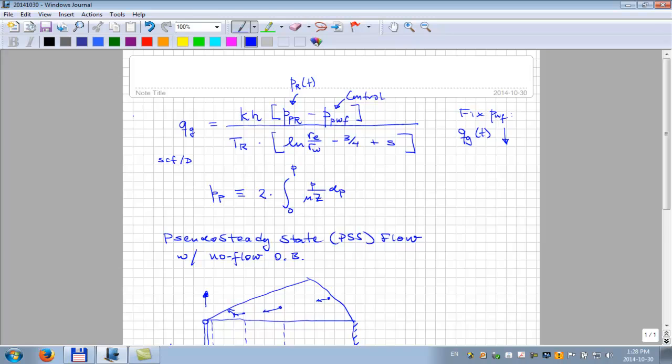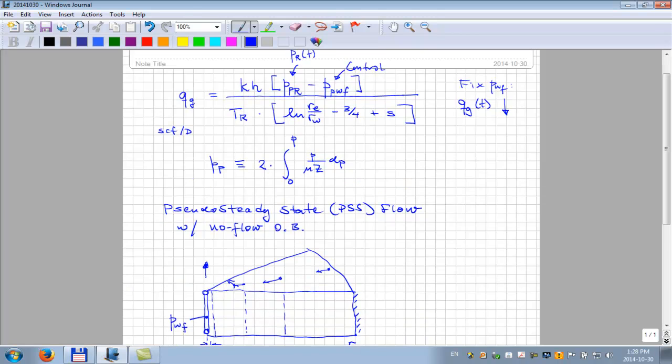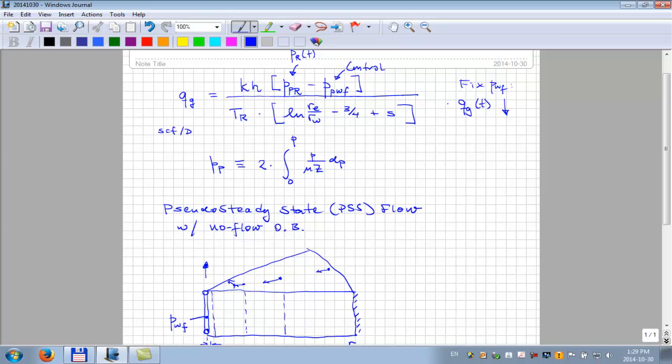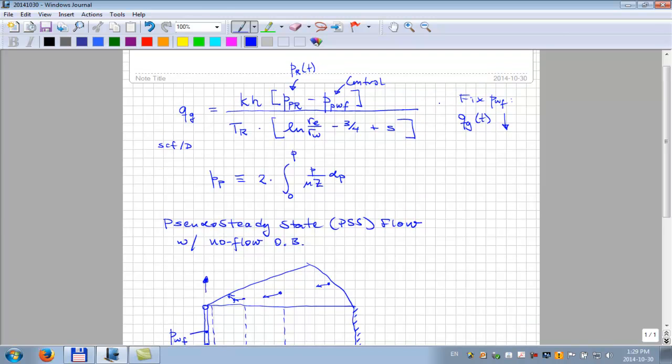Because you deplete the material balance. We're going to be talking about that, but that's what happens. You take something out, the pressure goes down. So the average pressure is going down. That is why you get the transient rate behavior. Transient means function of time. Okay, time dependence of rate. So are there any questions about that? That's what this is saying.